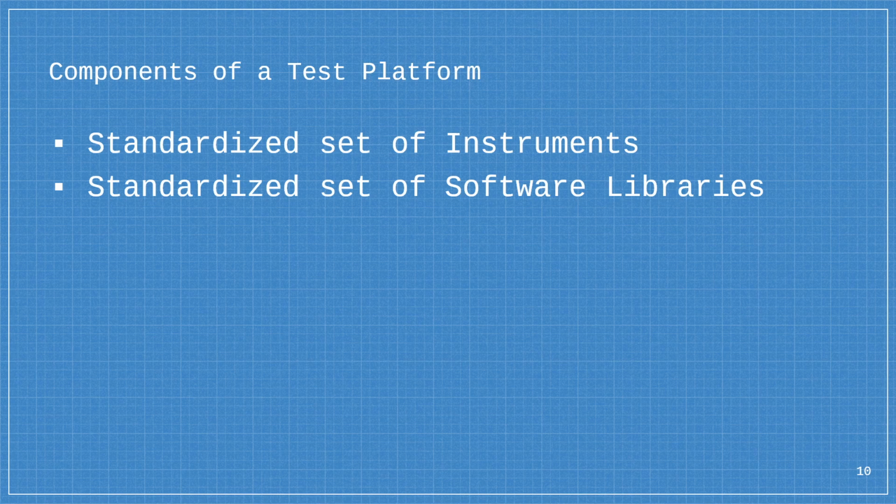and you don't call the individual implementations of those instruments, then that minimizes your rework in the long run, because when instruments go obsolete, if you set things up correctly, then you just pull out the old instrument, put in the new instrument, change the constructors so that you're using a new type of DMM, and then the rest of your validated test logic should work. You'll still need to do validation on that code, but it should minimize the amount of churn you need to do on it.